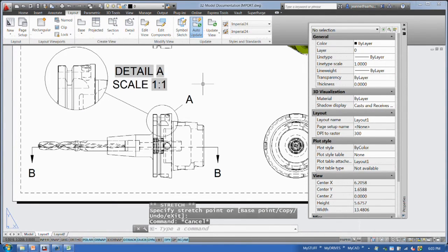It works with any, you mean drawing a detail, works with any model. Could you do that on a floor plan? I think you'd have to be using model documentation to create a model. You'd have to create a model documentation view, and then the answer would be yes. And the underlying geometry must be 3D. Yes, did you hear that? The underlying geometry must be 3D. Okay? But it's pretty cool. Okay.